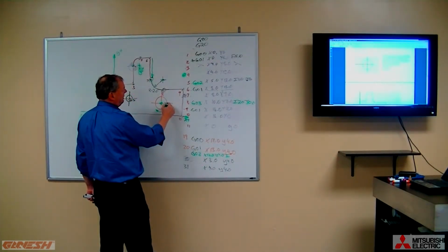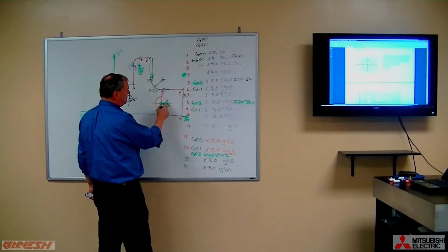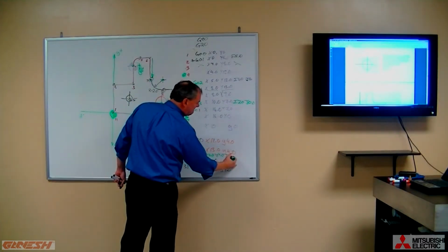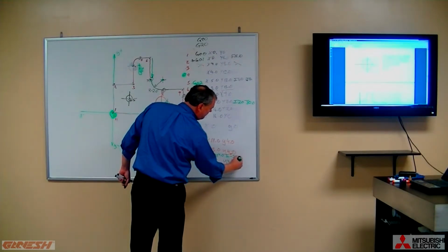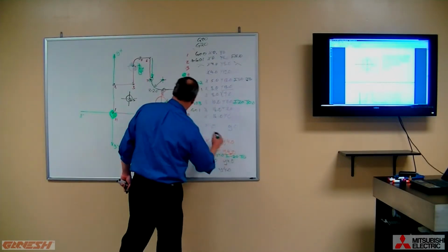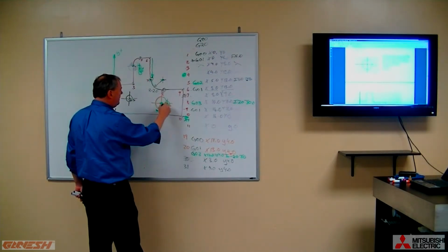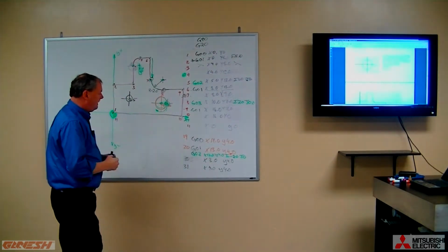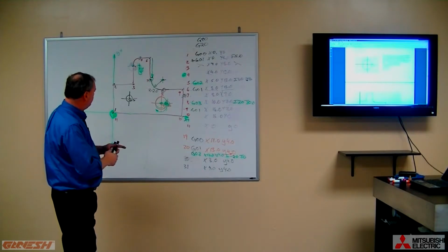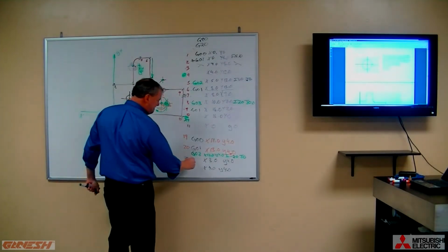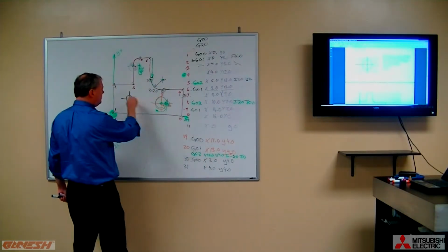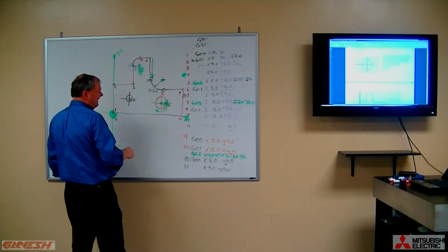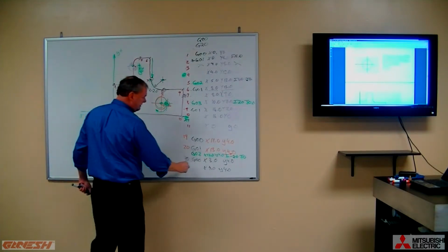Now we provide the I, just like we always have. If this is our temporary datum point, where is the I in relation to our temporary datum point? I minus, this is a 2-inch radius circle, so it's minus 2.0, J0. So then it goes and makes a very nice full circle cut. And now you probably want to say G00 over to point number 30. Always remember to reestablish your position. And then we do a G01 to point number 31.